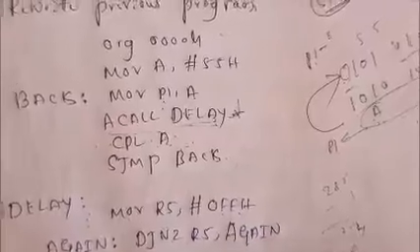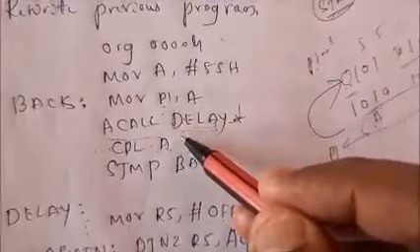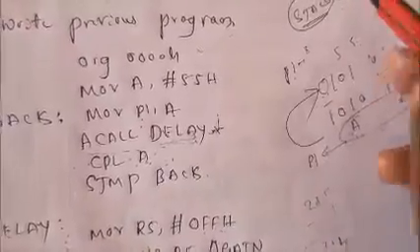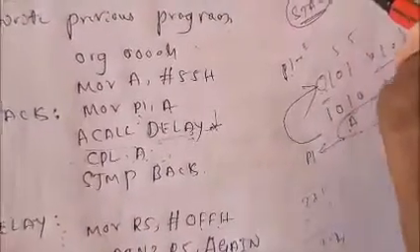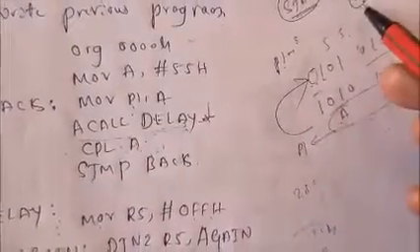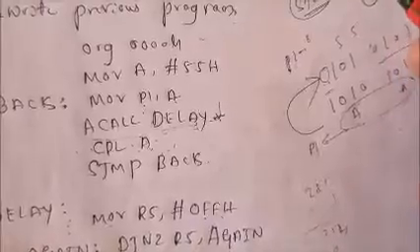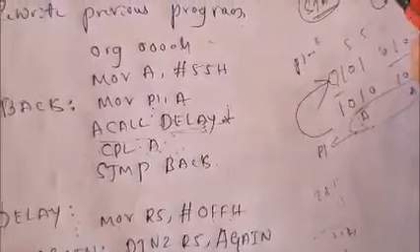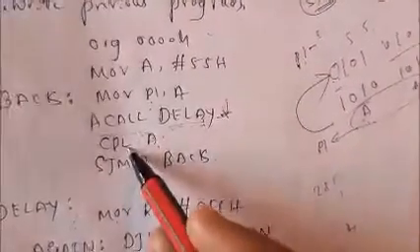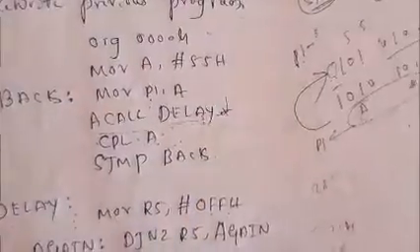Again where should I go for the forward line? That depends on the stack address. So that is nothing but the next instruction. This address is already in the stack here. So after completion of this one, it will perform the retrieval, or popping, of this address. Popping in the sense what will happen? Whatever address is there in the stack, it will pop out to the program counter. Once it is popped, it retrieves the program counter. That means the program counter knows that okay, I need to go for the execution of the instructions at this memory address. So what is this address? It is the next line itself. So again the flow will continue.